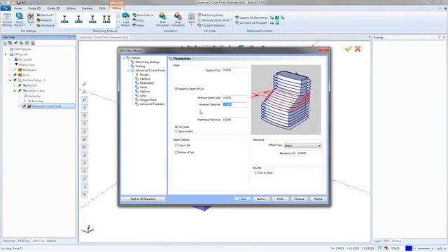And that's a big one because sometimes you start working on these flatter areas. You need a few more passes and you're able to come in and say, okay, if you don't hit your depth, so this is all about if it doesn't hit its depth. So if BobCAD sees that it cannot make its next cut at either the 5 thou level or the 20 thou level, and for it to hit that distance, it would have to go further than, in this case, say 100 thousandths to make that pass, the maximum step over is going to kick in before then. If we said put it at 50 thou, the tool is only going to travel at furthest 50 thou in, let's say, X or Y, but not Z, and that's where it's going to start its next pass.